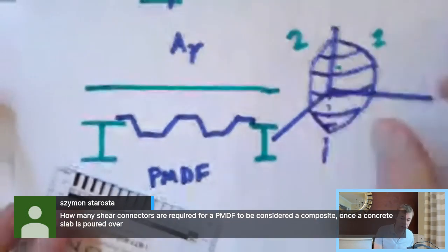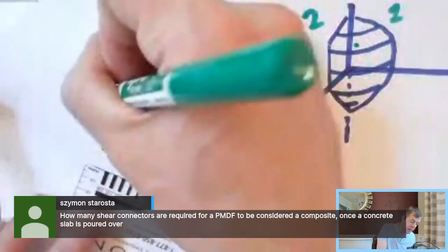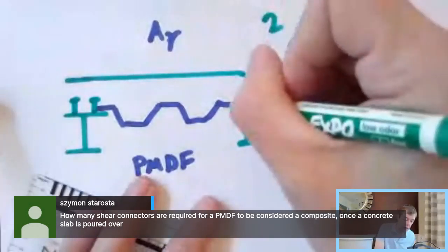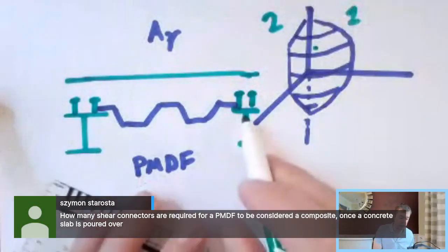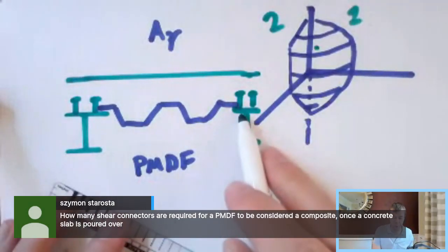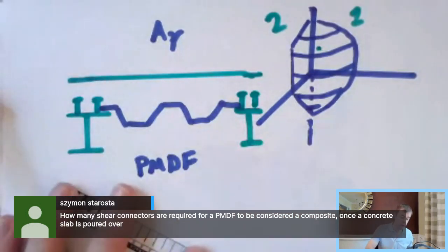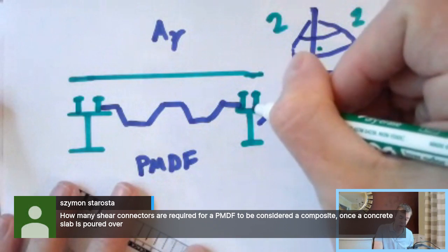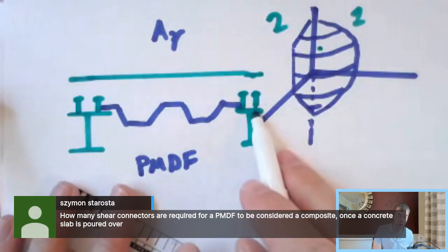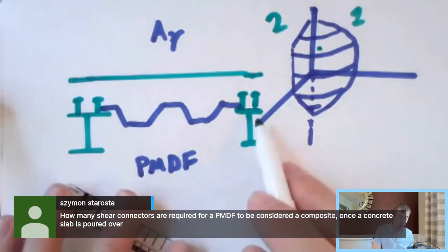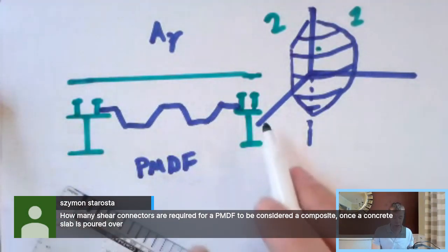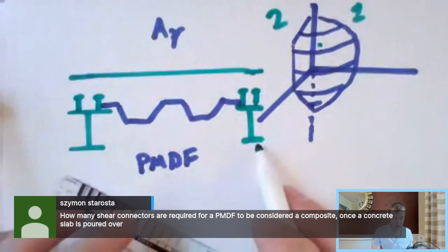What they're asking about is how to connect the beam to the concrete, and you use something called Nelson studs. They are actually welded to the top of the beam with a gun. So you come down there with a welding gun, you come down on the top and shoot it, and you create welds right there, friction welds, and then you cast concrete on top of that, and their job is to transfer the load from the concrete to the steel beam.